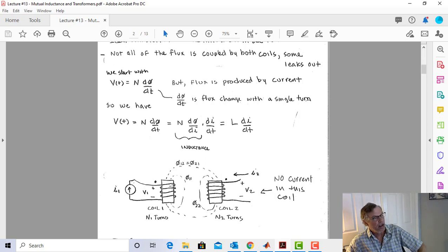It's not a great core, but it is ferromagnetic, and it's a pretty nice little core. It could be the little ferrite rod. If you pull a transistor radio apart and look at the antenna inside it, it's a ferrite rod. But the basic idea is these are separated in space. And this coil of wire is going to introduce flux in this ferrite rod. And it's all going to be in here.